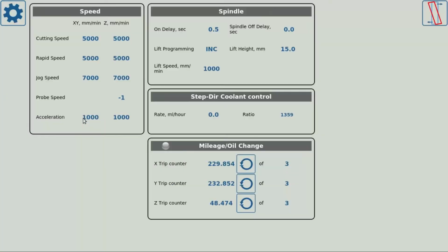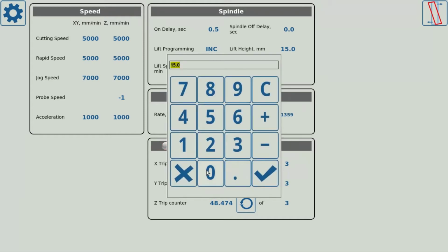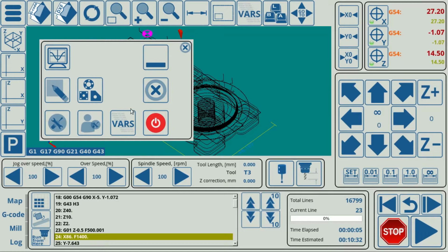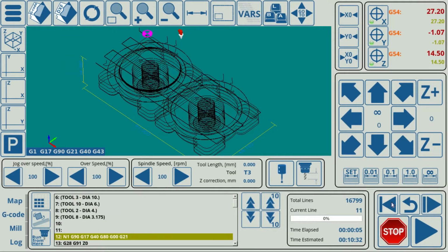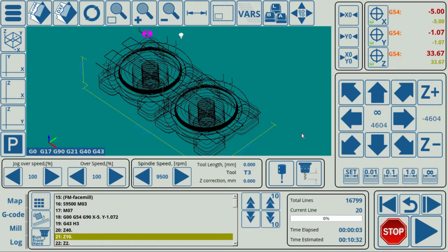If we remove our lift height value, set it to 0, and then reload and go back, we can see that when we stop our machine, our working point and our current point are indeed one and the same. And this is important because we did not leave the toolpath, and the machine will essentially start from the exact same point as it stopped, provided we don't move it.